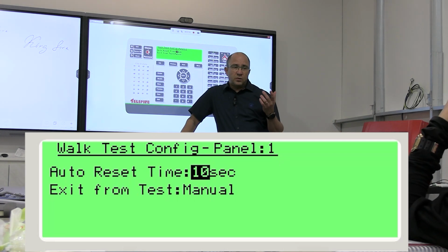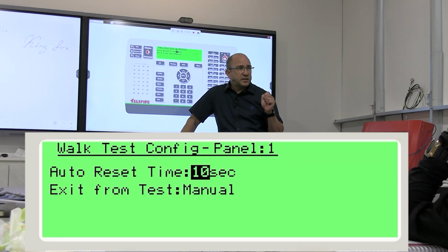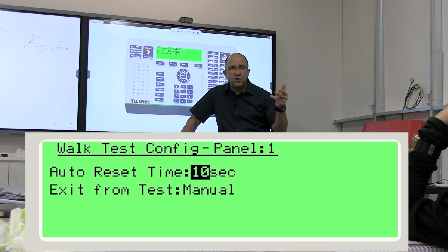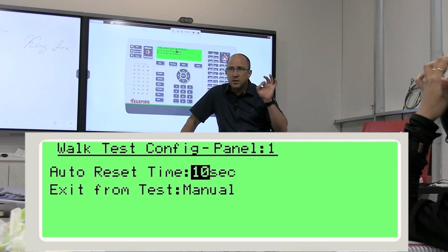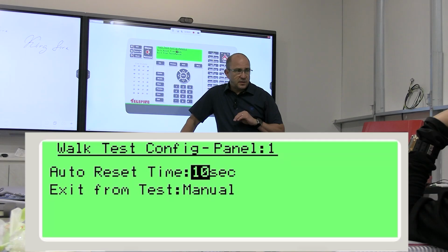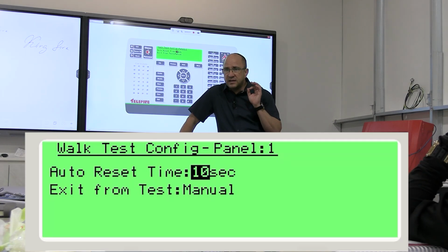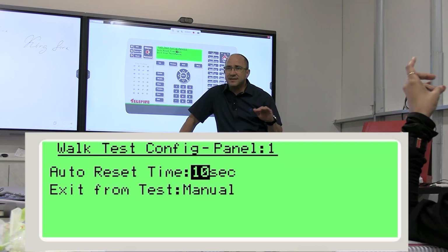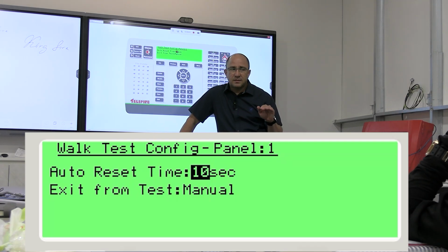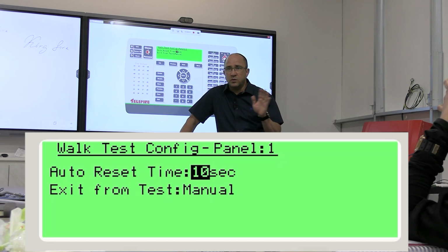When I go to the walk test, I switch on the detector. When I do walk test on loop number 1, for instance, loop number 2, 3, 4, 5, everything carries on working perfectly. Loop number 1, and listen carefully, when I put it in walk test, loop number 1 is dead. Dead. If there'll be fire where it is loop number 1, we won't know.